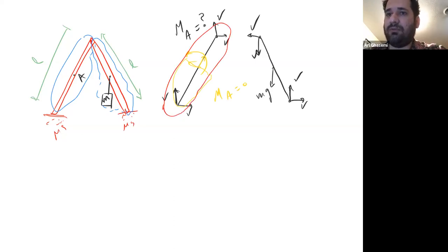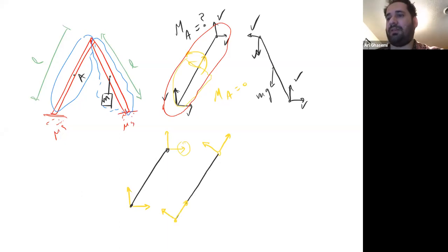The solution for that is by just considering this system. So if I take these 2 systems and consider only the beam on the left, then I realize that I only have a system like this, 2 unknowns here. And you know from the vector statics class that we can rotate these 2 unknowns. We can align it with the beam. So if that's my beam, I can also rotate this guy a little bit to the top right. So I can write my unknown like that. In fact, I could draw my FBD from the beginning like this, as you can see.